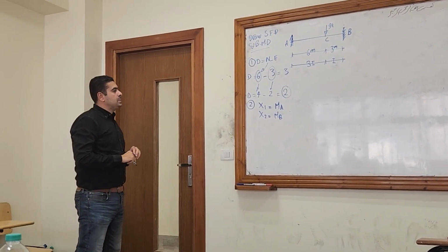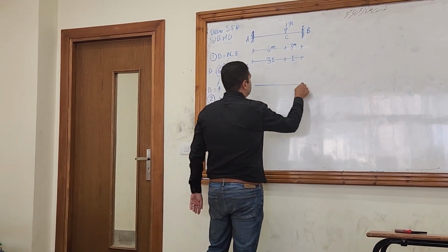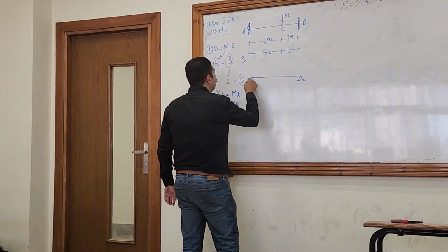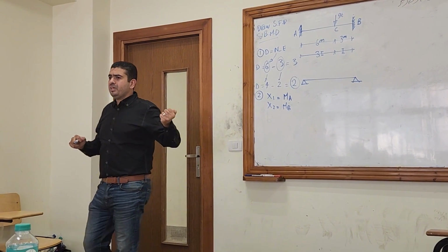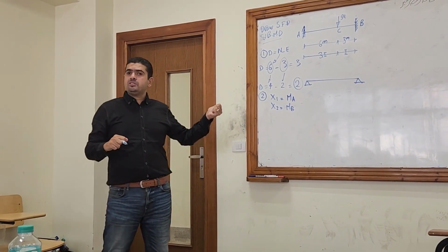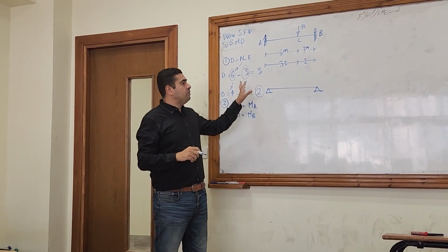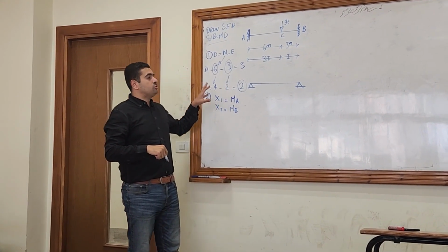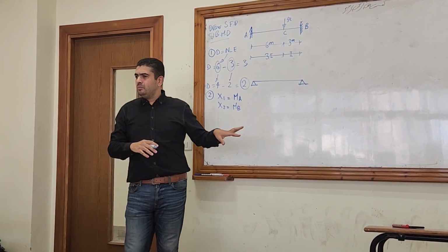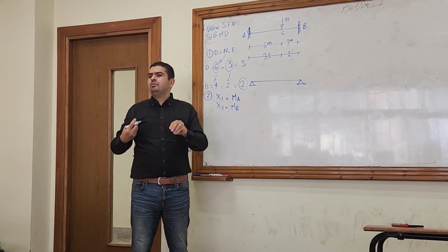Okay? So what will be the main system? It will look like this. It will be a simple beam. Not hinged. When you remove the moment at the fixed support, it turns to a hinged support, right? But as I told you before, in structure 2, we are not concentrating on the normal force, so it will not differ the roller support from the hinge support.